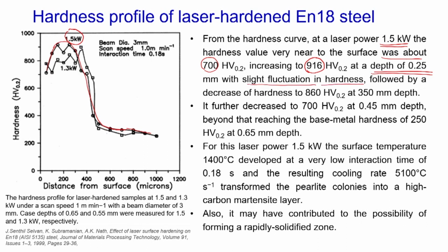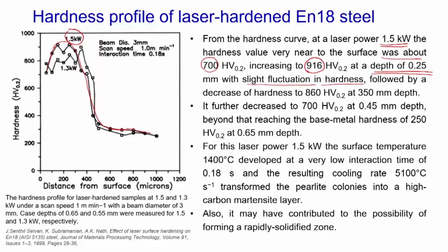Due to the different chemical composition of the material and the application of the force during the hardness measurement, we may get certain fluctuation when we are using the indent type of hardness tester. It is also dependent upon the grain orientation. If suppose the indentation is done in the voids, that also affects the value of hardness. So, there would be a slight fluctuation in the measurement of the hardness, that also has been noticed over here.